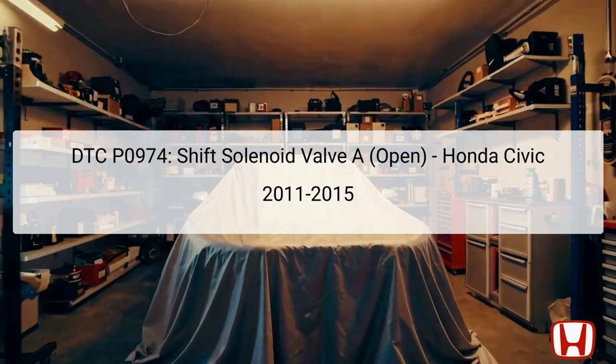The DTC P0974 indicates an issue with the Shift Solenoid Valve A, specifically an open condition. This diagnostic trouble code typically arises from an electrical circuit problem rather than a mechanical issue in the transmission. The shift solenoid is integral to the automatic transmission system, allowing the vehicle to change gears effectively based on electronic signals from the powertrain control module, PCM.